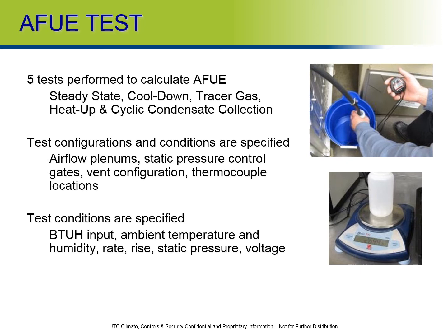The manufacturer has static pressure control gates, so they use vent dampers and things of that nature to pinpoint a static pressure level to get their airflow perfect through the system when they're doing their testing.